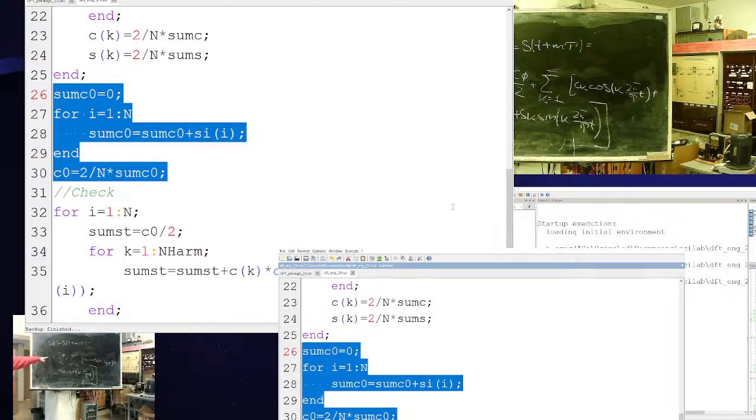This is the basics of Fourier's rule: I can substitute any periodic signal with a set of harmonics. If I perform this formula on my table, what should I get? The original signal. They should match, yes? If they do, this set is correct. If not, I did something wrong.